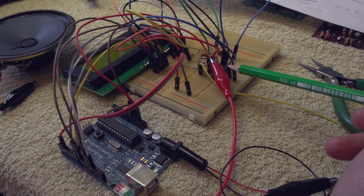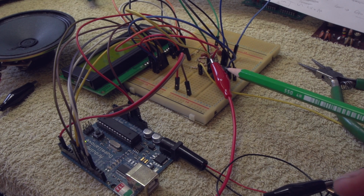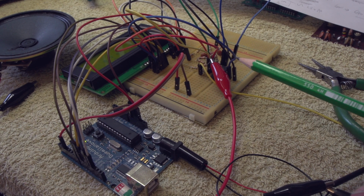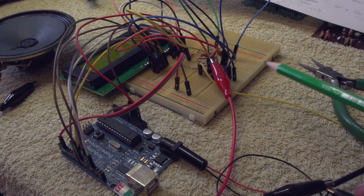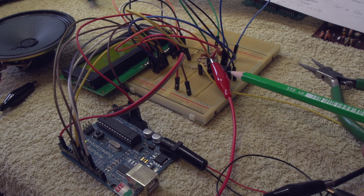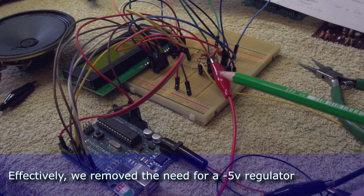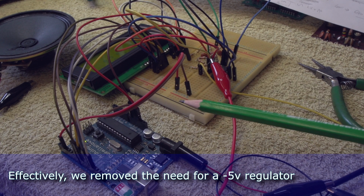That's the LM324 quad op amp, and of course the whole thing is running on 5 volts only as well, which is an improvement from the old board. If you remember, if you watched the original video that we did, it needed a -5 volt rail, and I decided it would be good if we can get rid of that and run the whole thing off 5 volts.